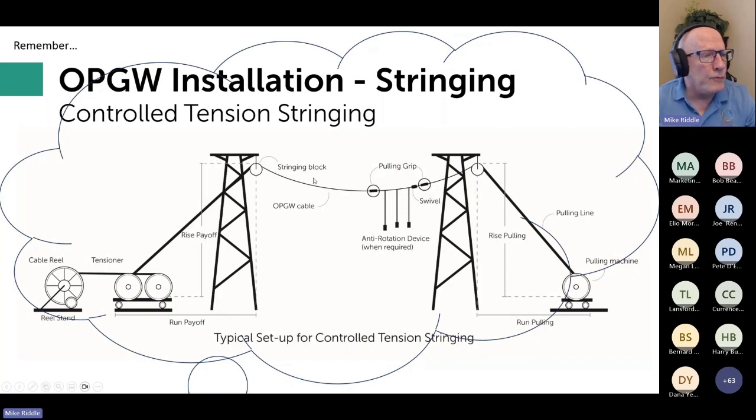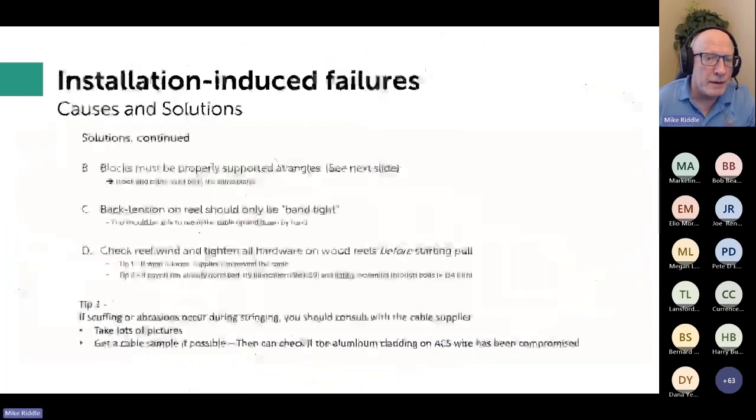I'll just go ahead and revert to this concept about the stringing blocks, because you see the diameter here. With a smaller diameter, I guess it's going to be easier to use this circle. If I'm applying a force here, it takes less force to overcome the inertia of this wheel than it does if I'm applying it here at the axle. And that's at the heart of what causes problems with the smaller stringing block.